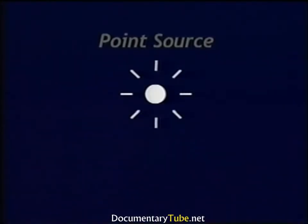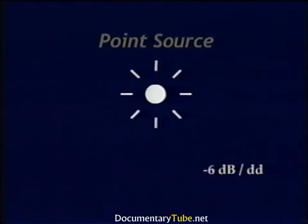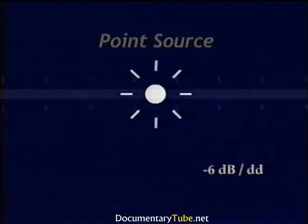Let's first talk about the sound source. We'll describe 2 basic sound source types and the relationship to highway traffic noise. A point source is defined as a source that's essentially concentrated at a single point from which noise propagates outward in all directions. In other words, sound radiates spherically from a point source. The sound levels measured from a point source decrease at a rate of 6 dB per doubling of distance. This is a decrease due to spherical spreading.